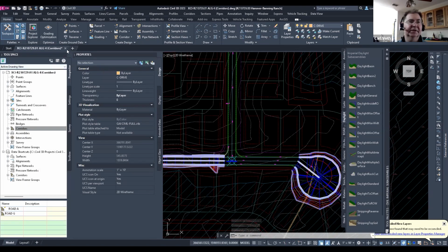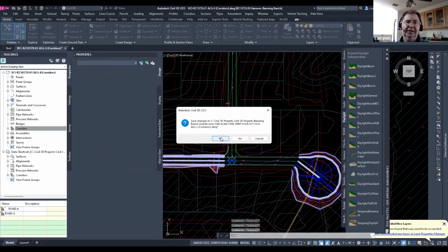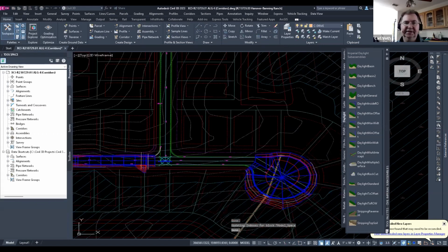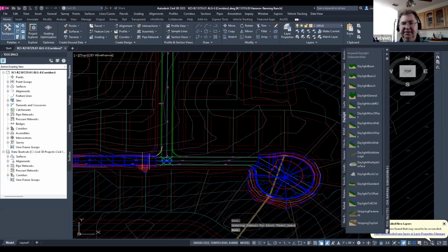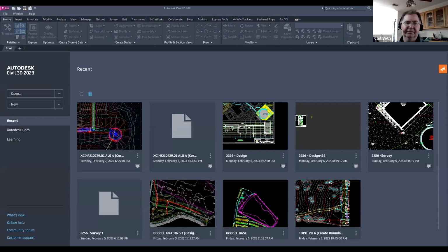All right, so let's go through and let's say that we've already completed our entire thing there in our subdivision. We're going to come back over through here, and now we have the option to, like I said, our developer actually only wants to build this section of our subdivision and not this right through here. I can come in, and first I'm going to split my corridor exactly and create a new region right there.